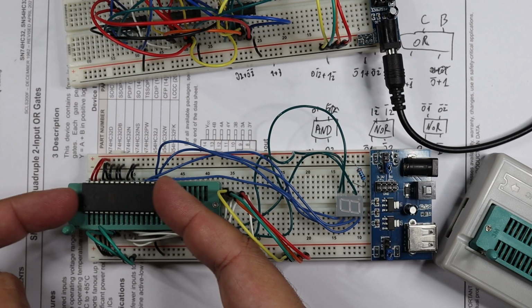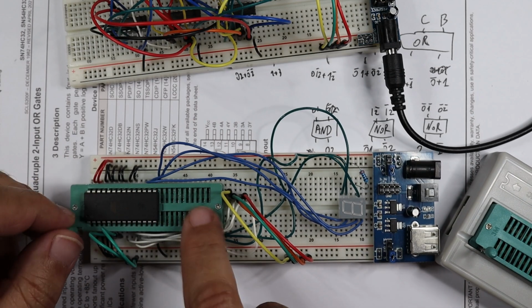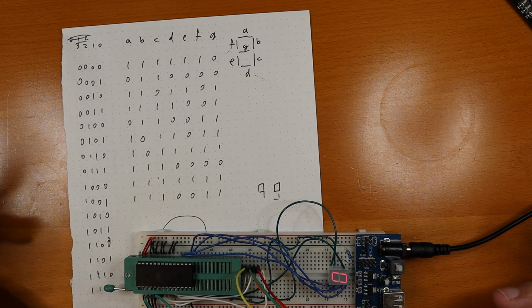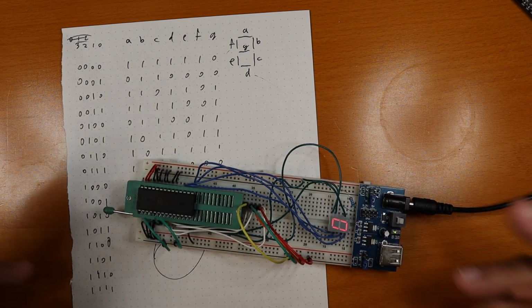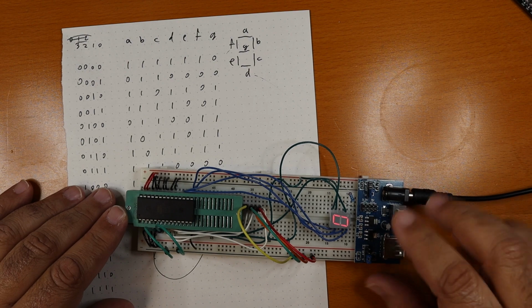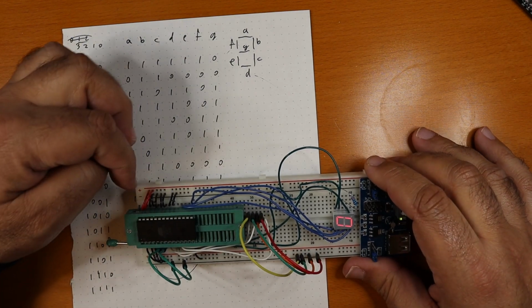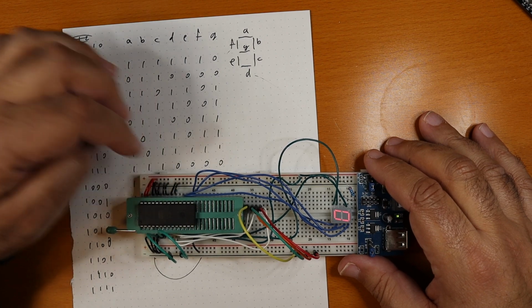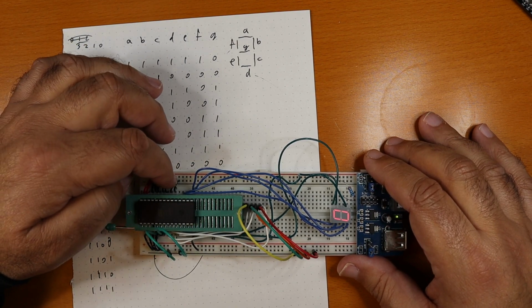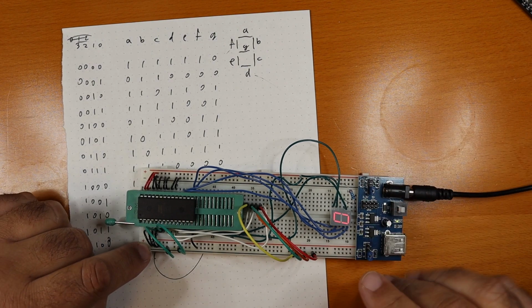Now, the 16 values cover just 16 bytes of the 32,000 bytes we have here, so we have plenty of room. So what I did is, almost all the lines here that you see as black, except for 2, are address lines that I tied low so that they wouldn't flicker.